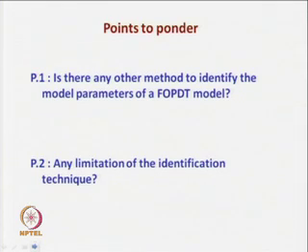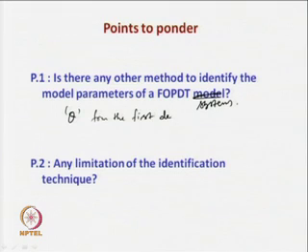Some points to ponder: is there any other method to identify the model parameters of first order plus dead time systems? Yes, there are many techniques. To name a few, one can estimate the time delay parameter from the first derivative of the sustained oscillatory output.